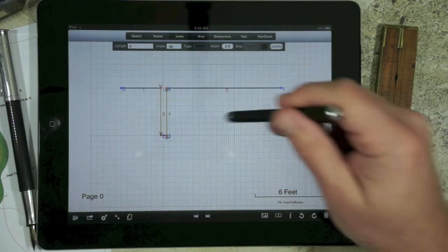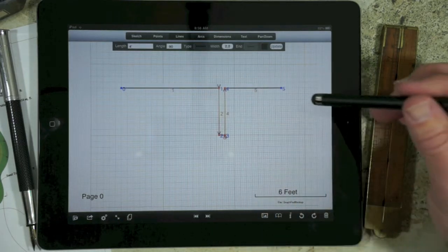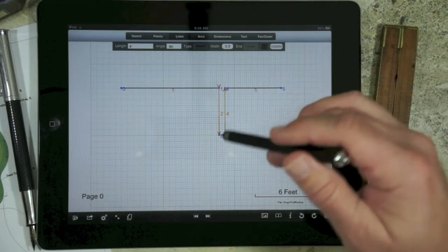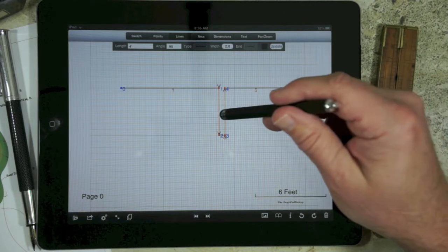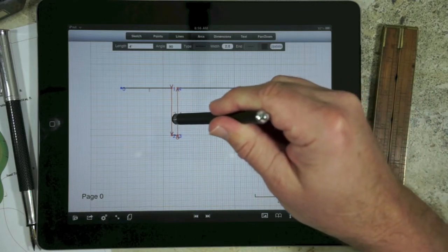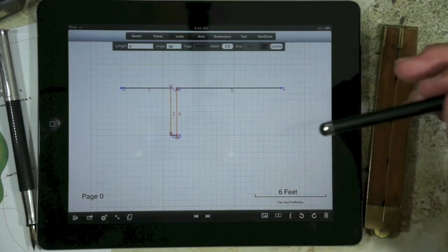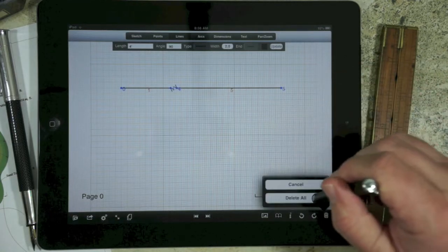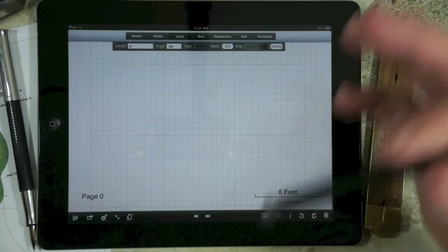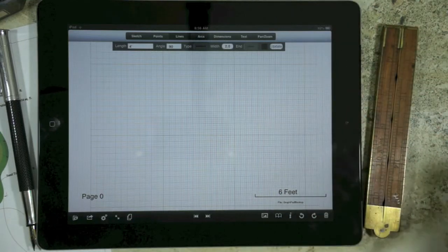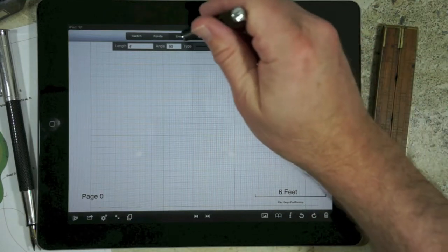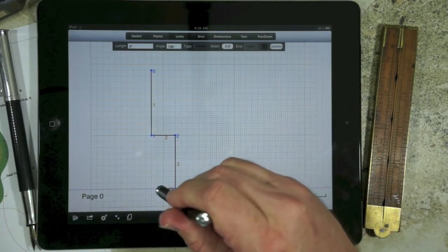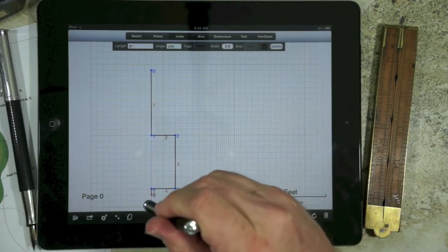So that brings out a very important point in that when we're trying to define a very precise geometry, it's easy to offset everything a long distance and then move it into position rather than trying to move it a very short distance. So that's very important when we're creating, say for example, we have a long wall and we have a bump out. To do that, what you do is you draw the larger dimensions and you bring that spacing out quite a bit.